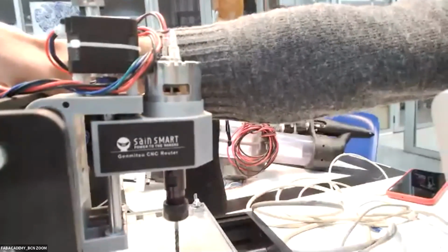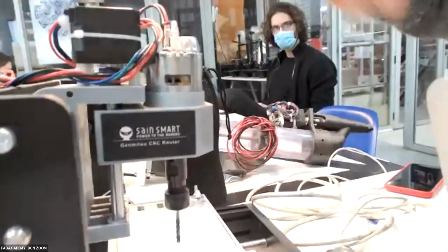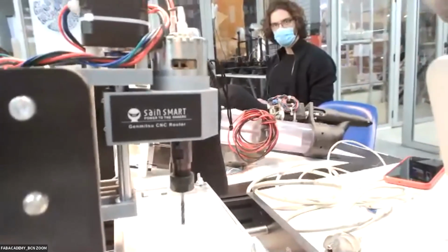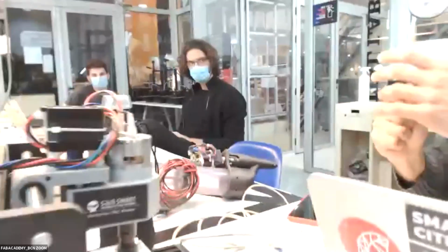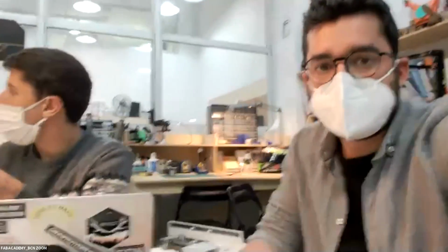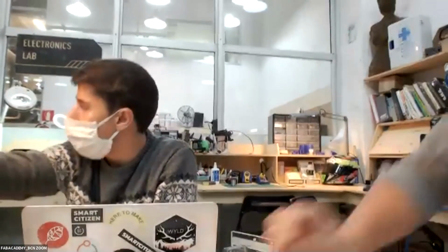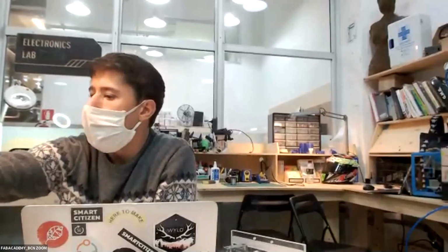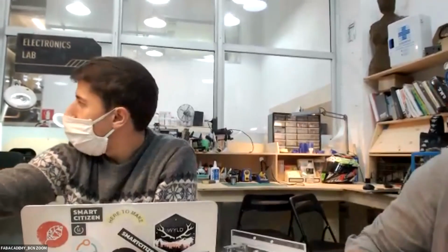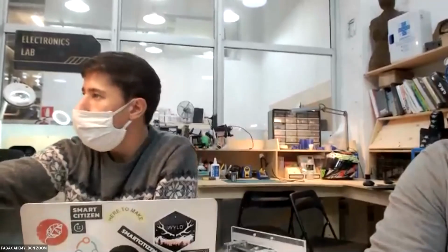That piece of code basically understands how the machine is built, and takes something like what we call a generic file, a G-code file, or a script of the instructions that we want to give to the machine to move, and translates it into movement of the machine. This code knows how big this axis is, how big this axis is, what is the ratio for every turn that we do here versus the amount of movement that we do there.